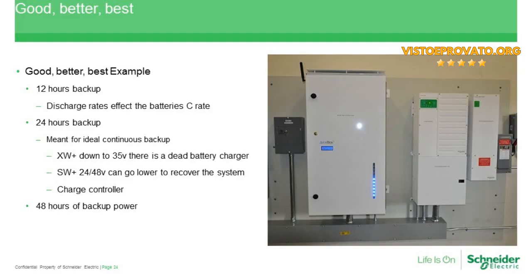One of the common questions that we get is whether or not you can do AC and DC coupling together, meaning that we have two charging sources. One is the grid tie inverters producing power from an array, and then let's say a wind turbine or solar on the DC side. We don't recommend that at this time.